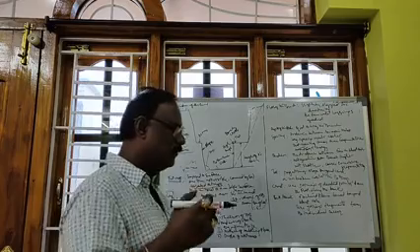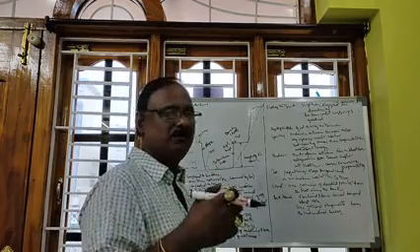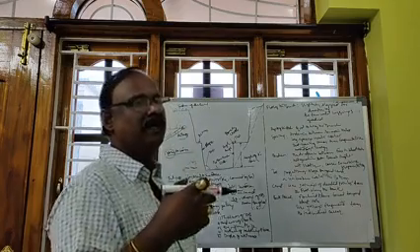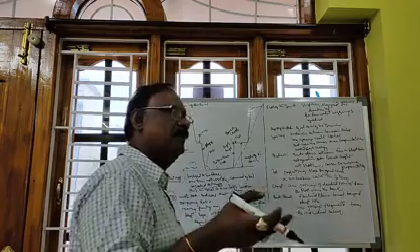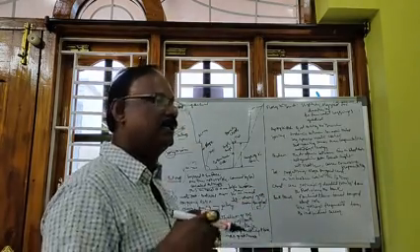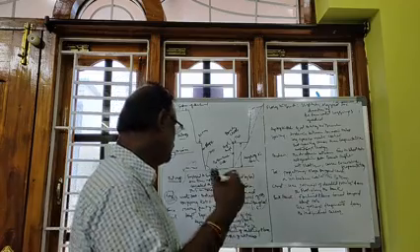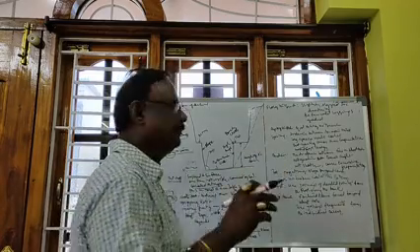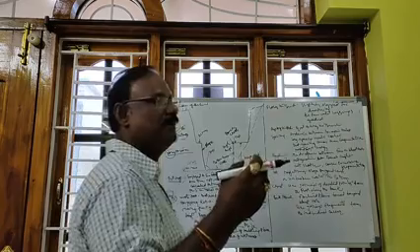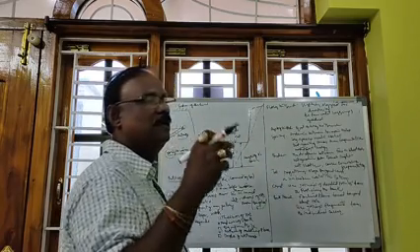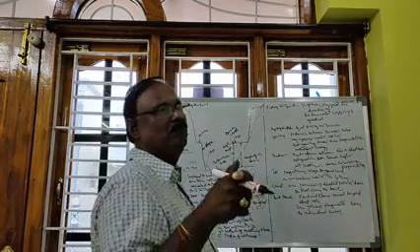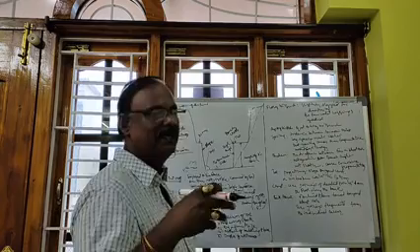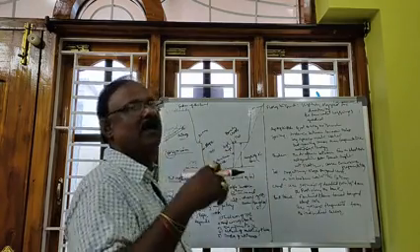When we are using bigger shovels, the boom of the shovel can lift even up to 30 meters, and then the height of the bench can be like that. Suppose a bucket wheel excavator, where a very lengthy boom is used, it can approach even 30 meters of height of the bench.